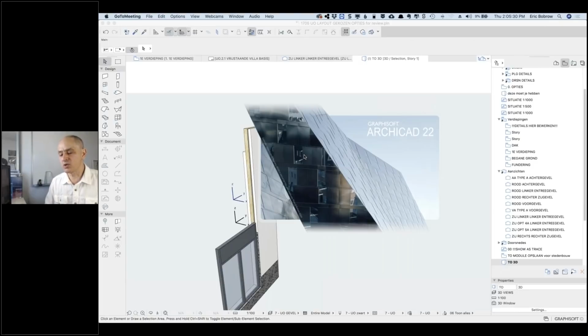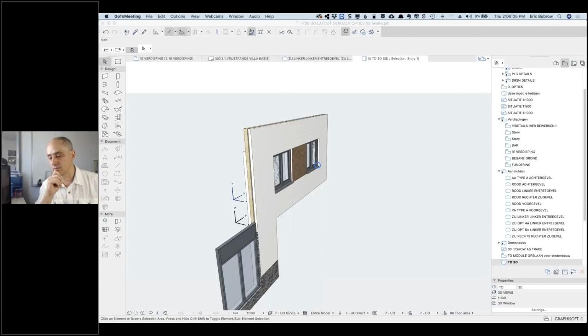You mentioned that there's an issue with seeing lines on the facade when you have interior walls meeting the element, meeting that wall. Yeah, I had a lot of lines, and in each situation there was something different going on. I had mistakenly made floors 3D, so they're floors with holes in them to spare concrete, and I 3D modeled them, but I saved them as walls instead of beams.